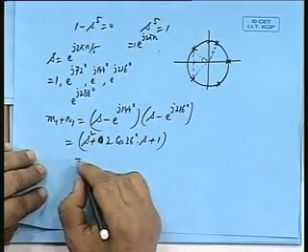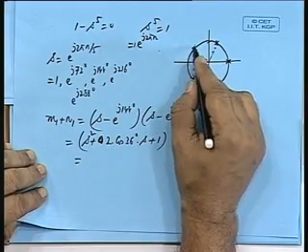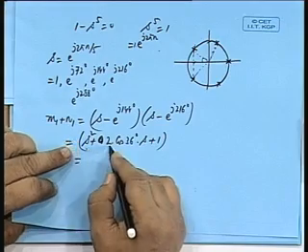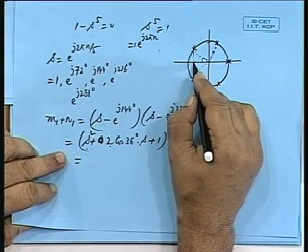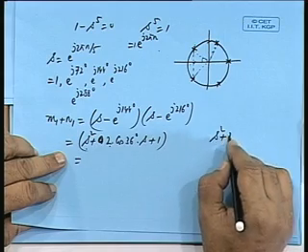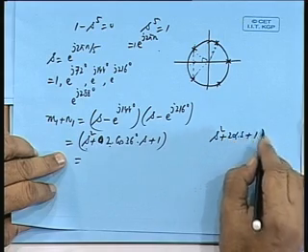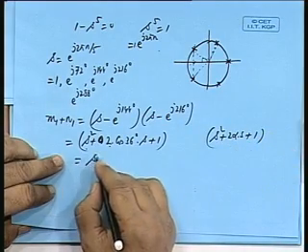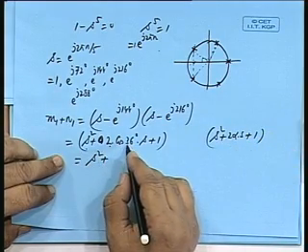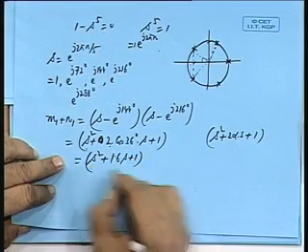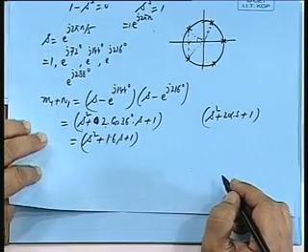Is that all right? Any quadratic coming out of a complex pair of roots on the unit circle will be s squared plus 2 into the real part, alpha, into s plus 1, since alpha square plus beta squared is 1. So, it is s squared plus cos 36 degrees is approximately 0.8, so 1.6 s plus 1.